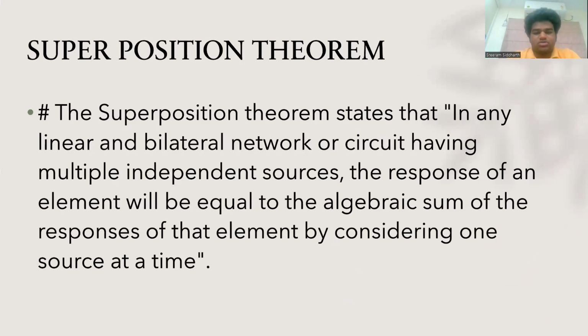The superposition theorem states that in any linear and bilateral network or circuit having multiple independent sources, the response of an element will be equal to the algebraic sum of the responses of that element by considering one source at a time. By short circuiting or using open terminals, we can find the response of an element. So that's the superposition theorem.